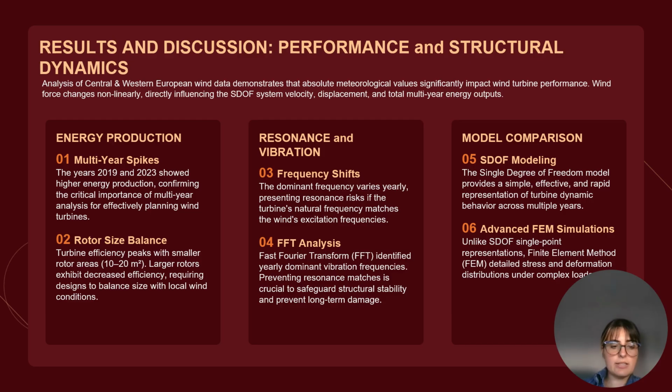The rotor size balance is also very important, and our research shows that smaller rotor areas are better than larger ones, because when you have a larger rotor area, we need stronger wind in order to move the turbines, and the result might be smaller production. So we need to be very careful which sizes of turbines we put in what location, based on the winds.